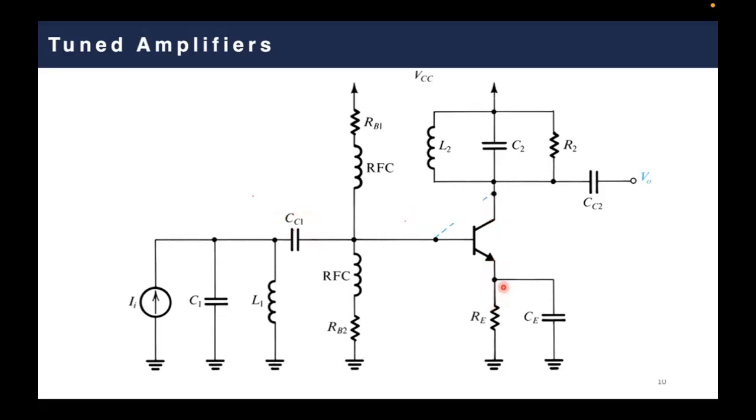We have a common source. Usually we know that we have some sort of a bypassing capacitor. As you can see, this one and this one, these are bypassing capacitors cascading the system just to get rid of any DC offsets. Then we have this double filter effect. So this is simply the input. Then you have an LC filter, which is a band stop filter to make sure that you are getting rid of any undesired or unneeded noise from your circuit.